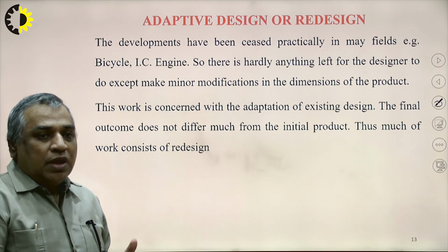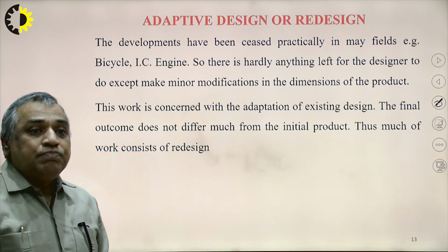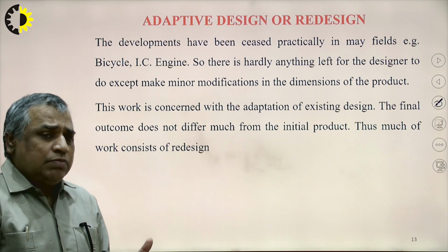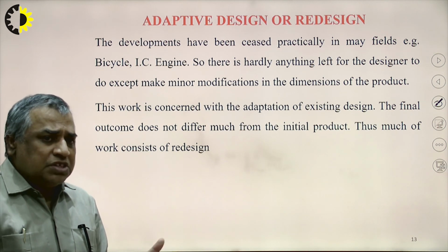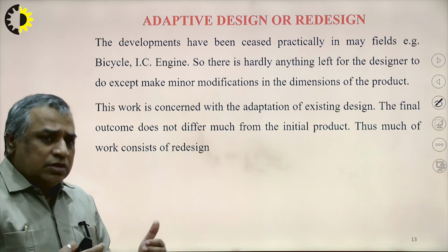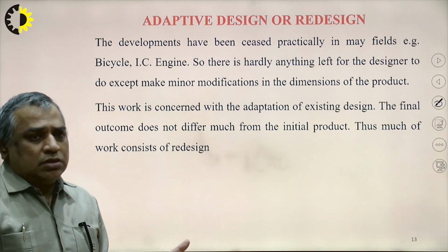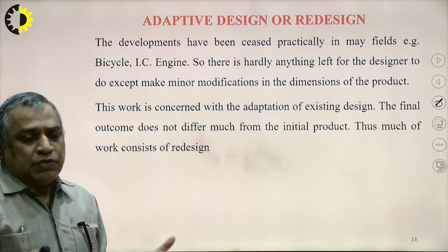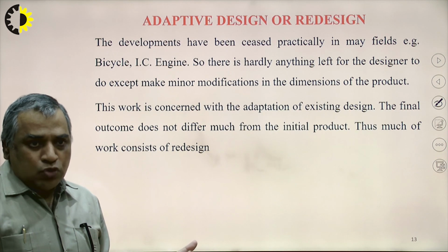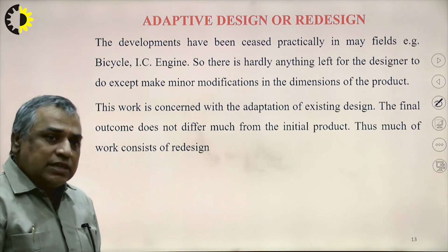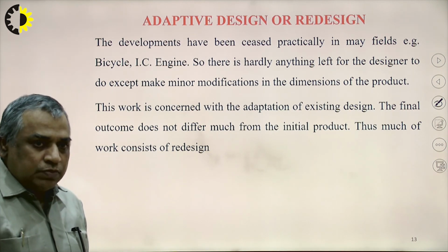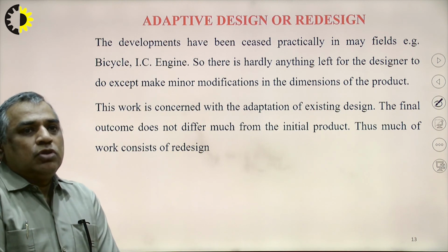If you want to get more force from a hydraulic piston, the piston diameter should be more. Having the same pressure, you will get more force, or you will increase the pressure to get more force on the piston.